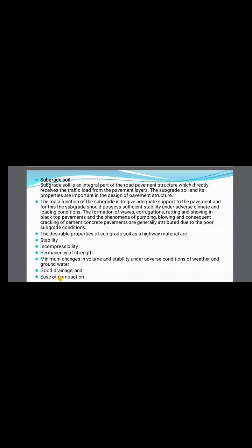The formation of waves, corrugations, rutting and showing in black top pavement, and the phenomena of pumping, blowing, and the consequent cracking of cement concrete pavements are generally attributed to poor subgrade conditions.